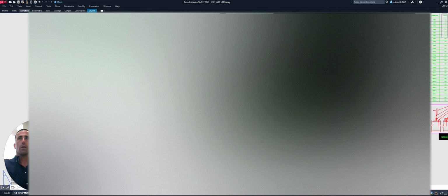Site class is D. We use stiff soil. We do not have a report. The seismic design category for this project is D, and that information comes from ASCE 7-16, table 11.6-1. So anytime the SDS value is greater than 0.5, then you're in category D.